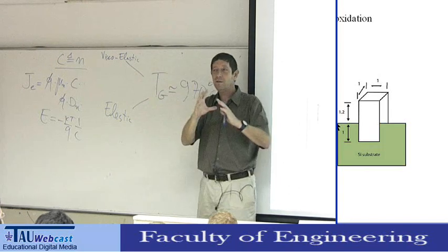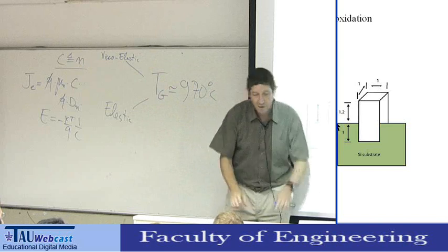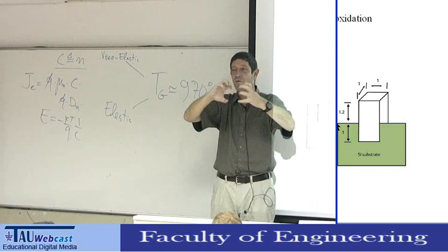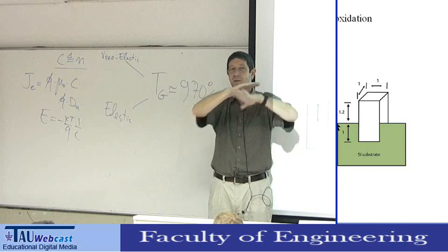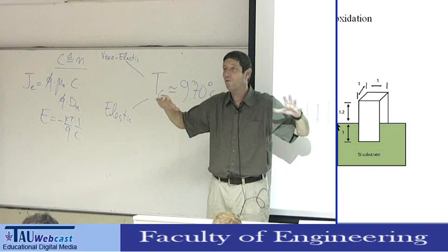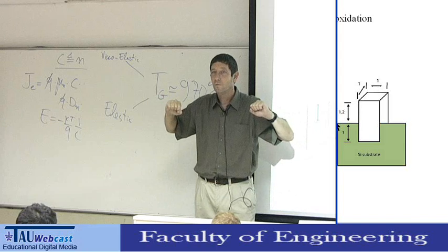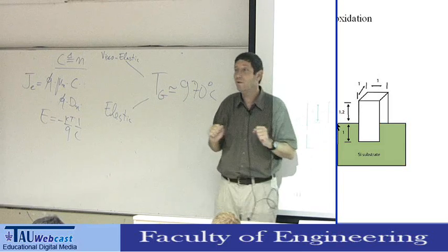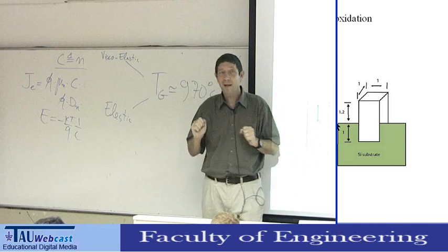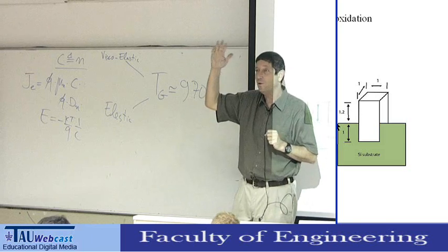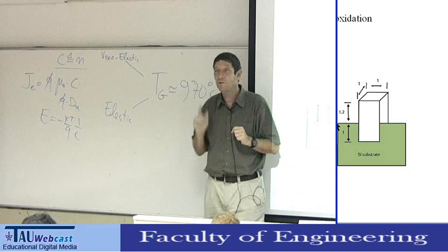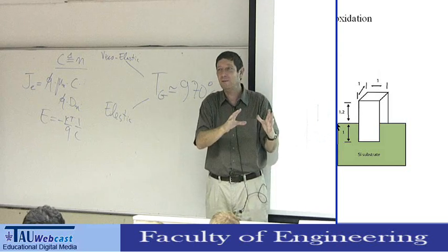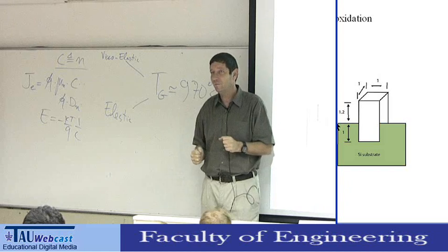But you can think about it as at a certain point all the bonds are connected. If you heat up the structure, some of the bonds are released. Then the material behaves more like a viscous fluid. It can flow, but it's still a solid. So it's a solid reflow. It's not a liquid. The melting point is actually something like 1400 something degrees Celsius. So it's not melting. It's just a transition from a completely elastic material to a viscoelastic material.